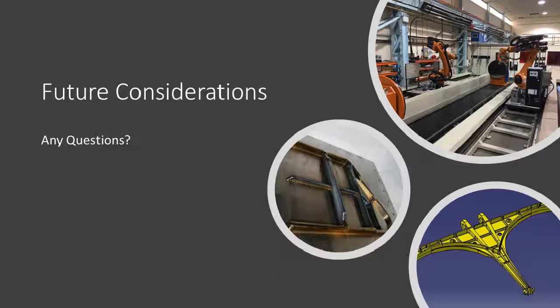No. So although there may be the inclusion of AM, and again, I'll stress that we're Tornado engineers, obviously our unmanned aerial vehicles still have that same criticality, even though there's nobody in the cockpit. Actually, in terms of the risk to life and the seriousness that we give the argument, it's everyone below the aircraft. So I would think that we would accept no more risk on our UAVs, and therefore we'd only stay in line with what's currently cleared, and I don't believe we've cleared any structural components, so no.